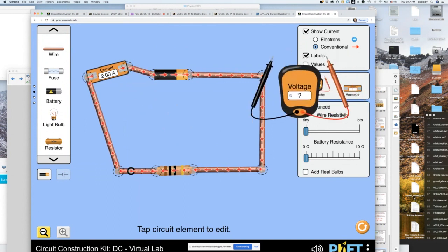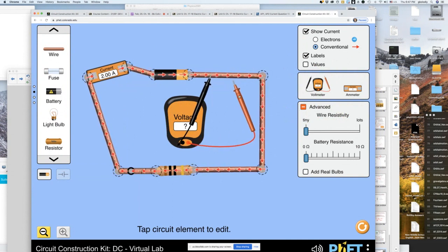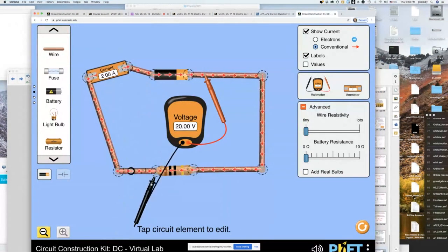If you want to measure the voltage, you have to measure it across something. Like, for example, if you measure the voltage from here to here, this actually gives you the voltage difference. There's no voltage difference. But if you want to measure the voltage, let's say across the battery, like I have here, you can put this anywhere over here or here, or even down here, until you get to the resistor. So you measure the voltage across here. You can measure the voltage across the resistor, okay? And the voltage is the same because this is the only thing that's flowing in this circuit.